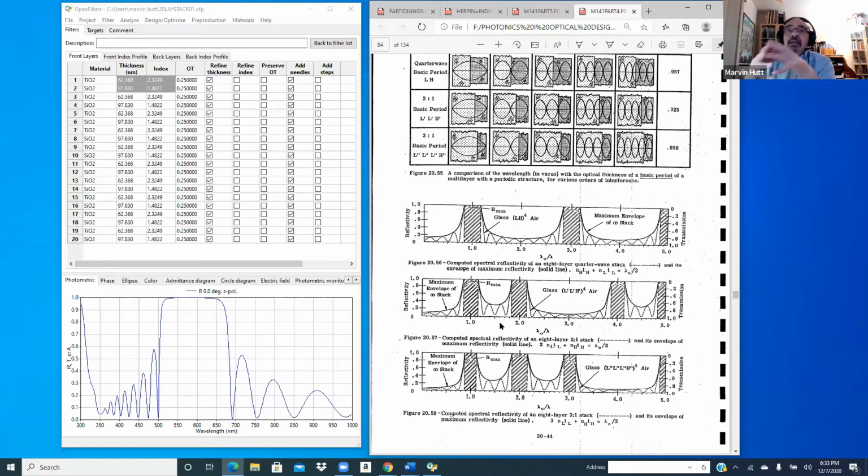Well, the main laser is 106, and you're going to hit a crystal inside the laser with 106, and the crystal is going to double and produce 5300. And you want the laser to laze at both 106 and 5300 simultaneously, right? So you need high reflectivity mirrors that are 99.99% simultaneously at 106 and 5300.